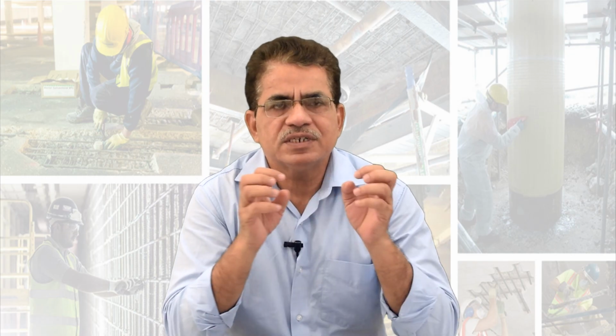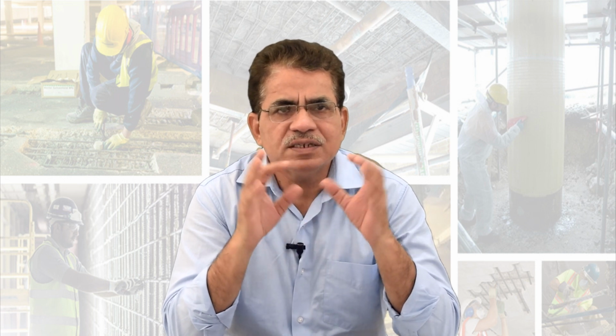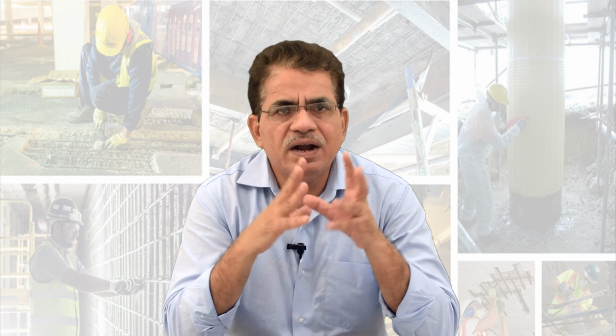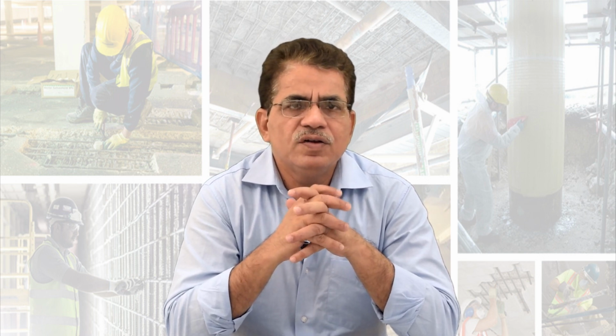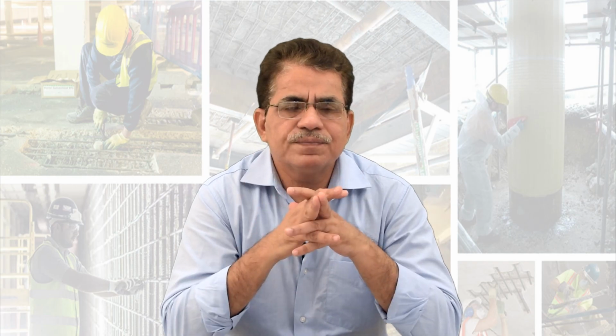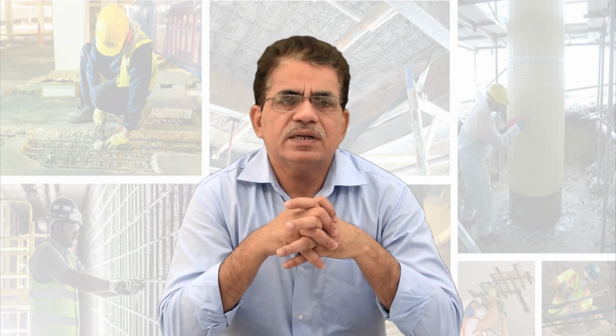If some underground streams are there, they can wash out the finer particles of the sandy soil, and due to that there will be undermining of the foundations, and failure or settlement of foundation will occur. Then flooding or leaky drains. If drains are leaking, then certainly it is going to cause problems in the building.